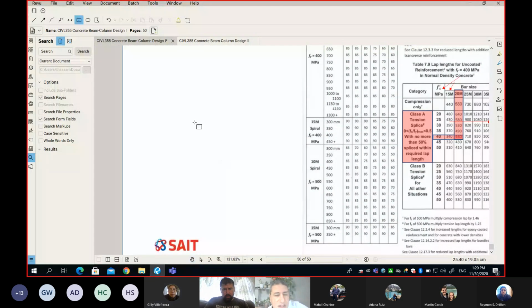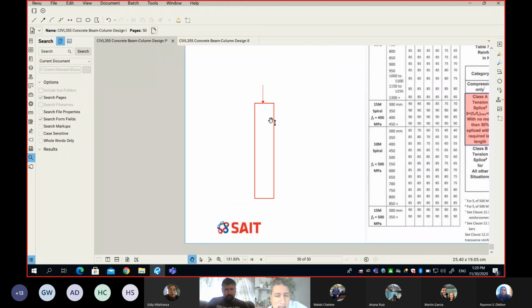Okay, so here is a side view of your columns. Here is a column. Of course, if my column is a centric column, which means my load is acting at the centroid, then the stress over the entire cross section is compression, which means all the rebar, whether on this side or on this side, both of them will be in compression.